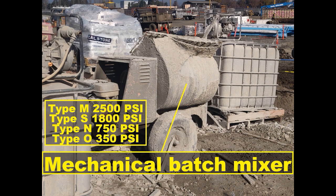Type M mortar provides at least 2,500 psi, Type S 1,800 psi, Type N 750 psi and Type O 350 psi at 28 days. For field batched mortar, measure component materials by volume. Use measuring boxes for materials that do not come in packages, such as sand, for consistent batching.